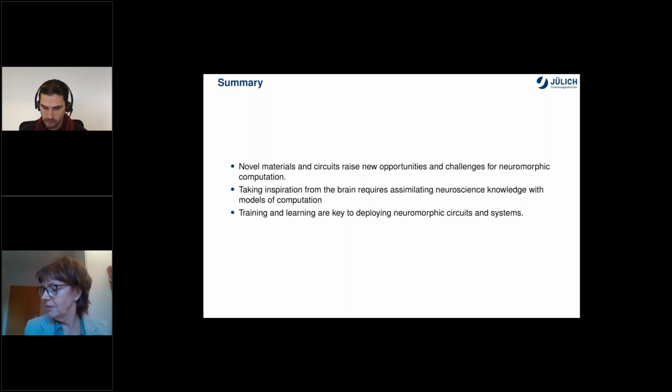We have one question concerning STDP. I mean, you clearly said you need volatile devices to have a useful STDP-based learning rule. But if you have a look in the literature, you find hundreds of papers of people using non-volatile devices and showing STDP by overlapping pulses. So what is your opinion of this? Do you think it can be useful, irrespective of the fact that it does not really contain the time information?